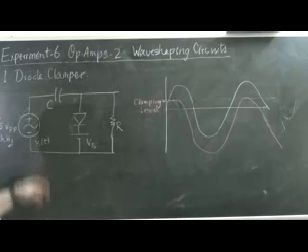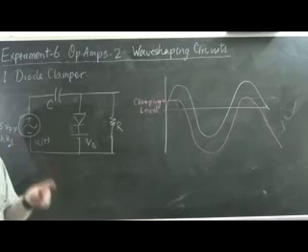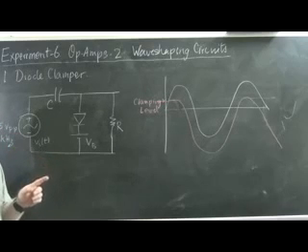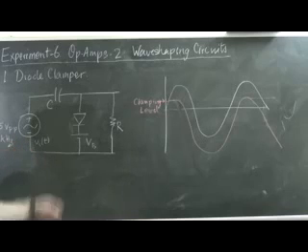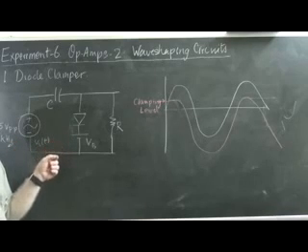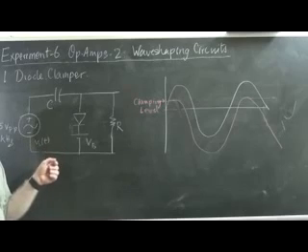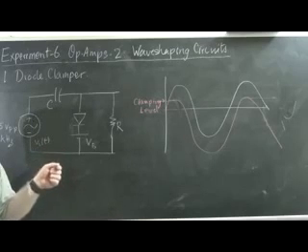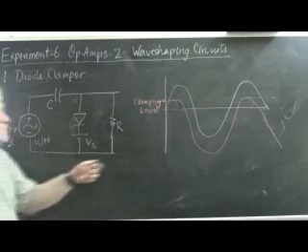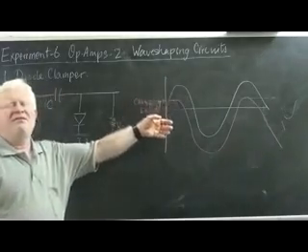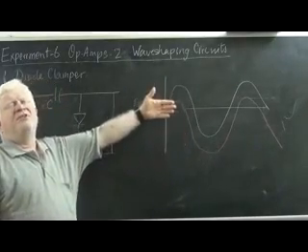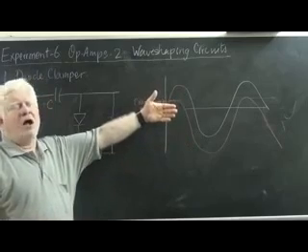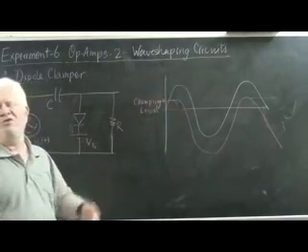Ideally you should really put both the input and the output onto the screen in DC mode so that you can see the DC voltage difference. You might even be able to have an adjustable source over here and you can adjust that voltage and see how after a few cycles the clamping voltage readjusts itself and the waveform of the output shifts its DC position to adapt to the new battery voltage.